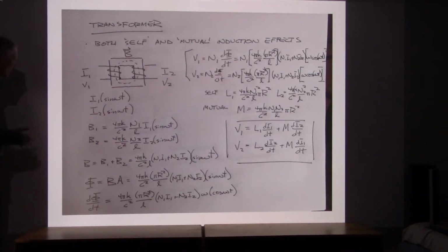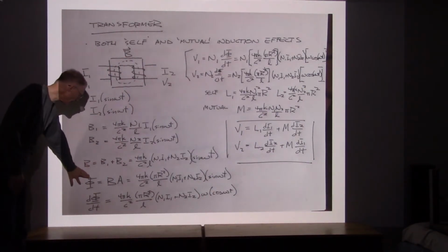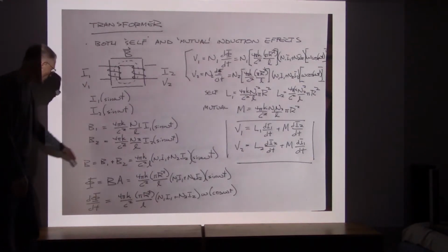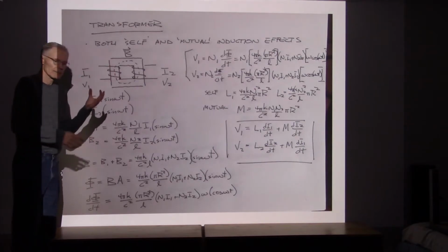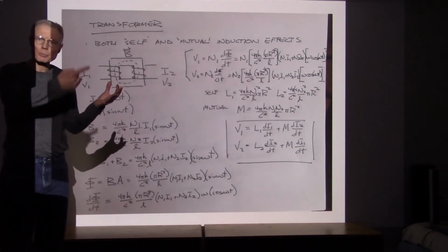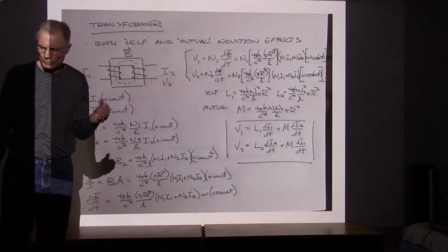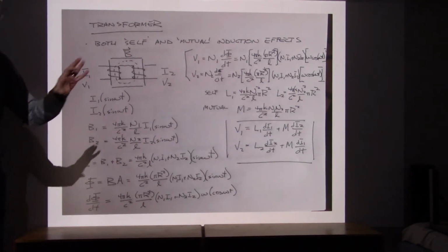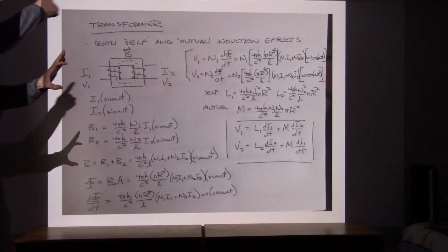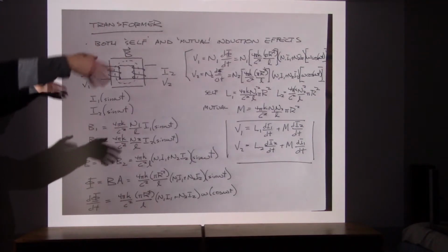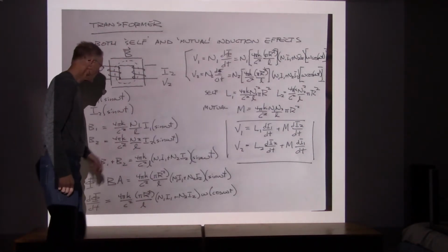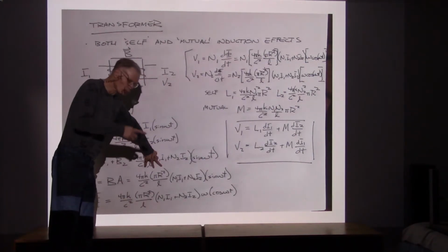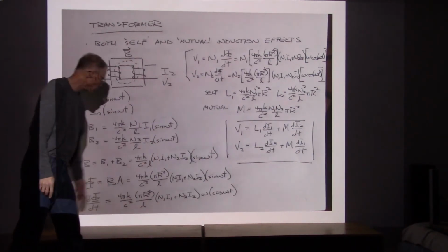All right. From the magnetic field, then I can calculate the flux. Now remember, when we calculate this flux, it's how much flux each one of the loops is going to wrap itself around. So the flux that we set up inside that iron ring is given by B times A, and we'll say that it's a circular cross-section, pi r squared.